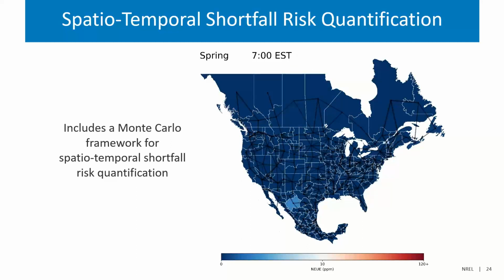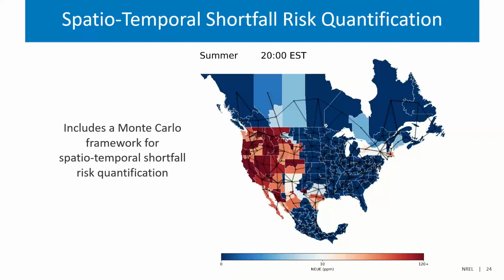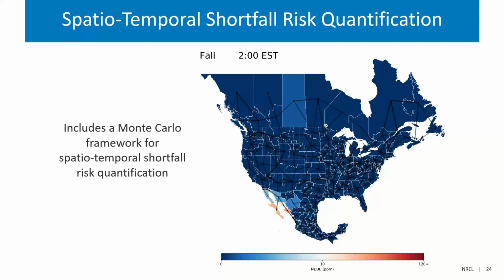You would not really know how much a 100 megawatt wind farm would contribute unless you look into the capacity credit. And a 100 megawatt wind farm can give you different capacity credit depending on which region you're installing it in, because it depends on the load, on transmission, and a couple of other things.